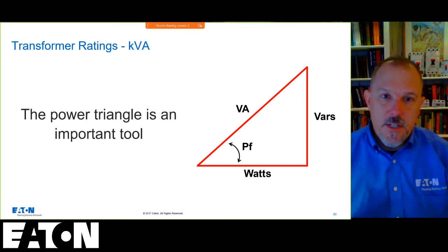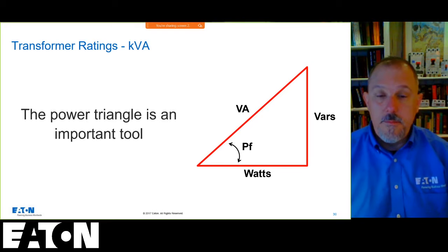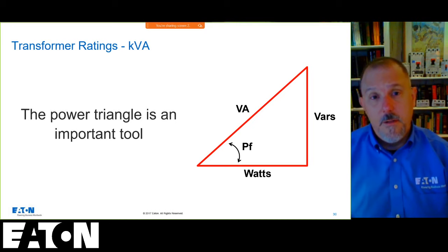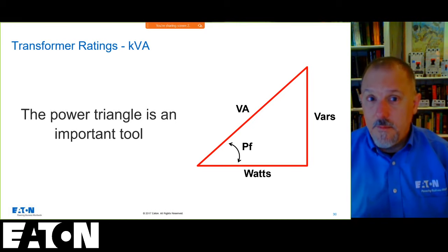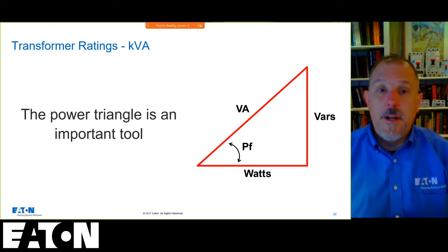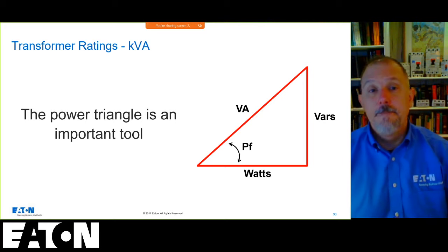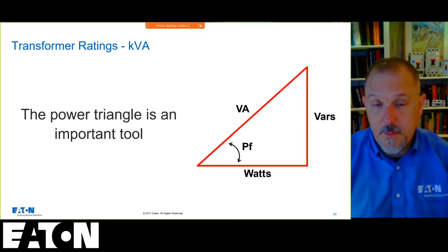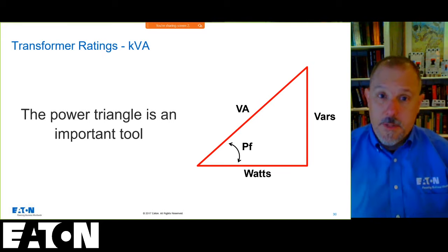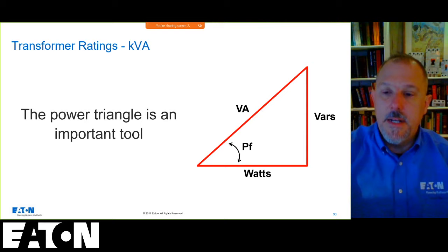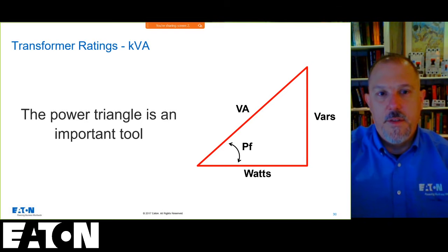We take watts and VARs into consideration, and we will size our transformer for VA, not for watts, and not just for VARs. So, I can do power factor correction and whatnot. If I do my power factor correction on the secondary, I can say, well, I'm supplying less VA. Again, I know some people that have done that in the past. Supply your VARs locally. You can reduce the size of conductors, etc. But in any case, we size transformers on VA.